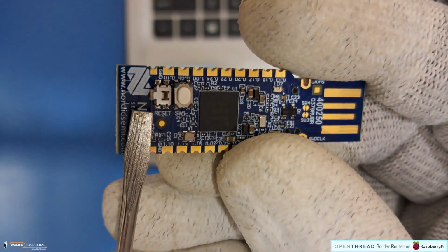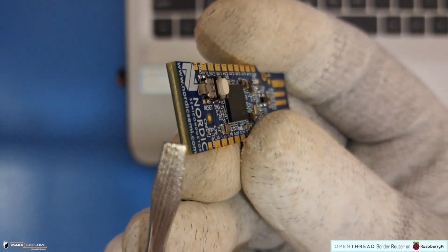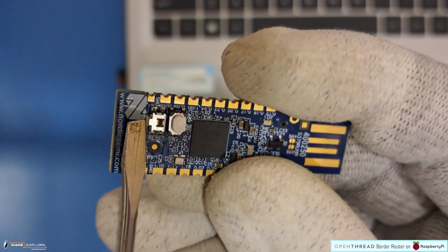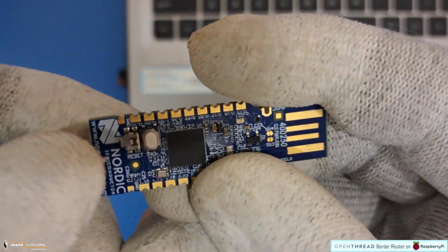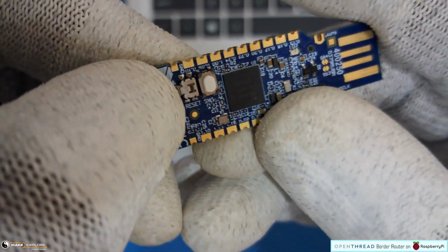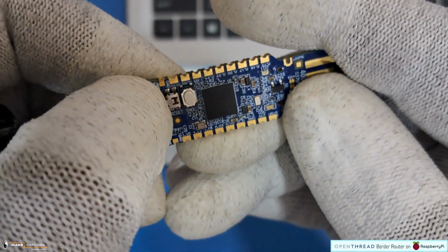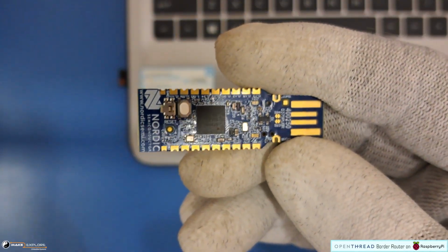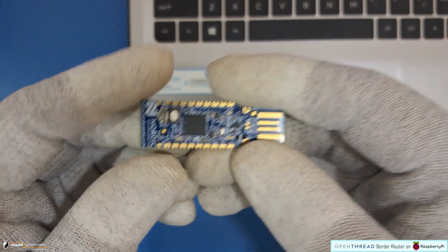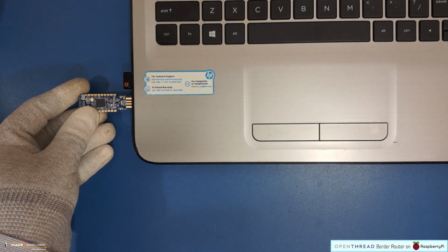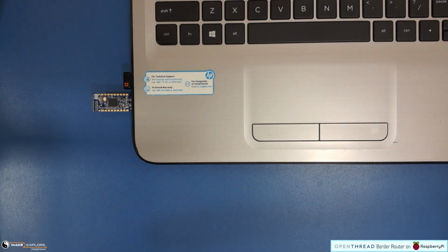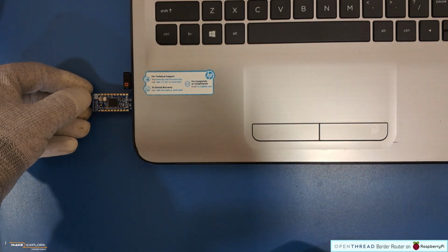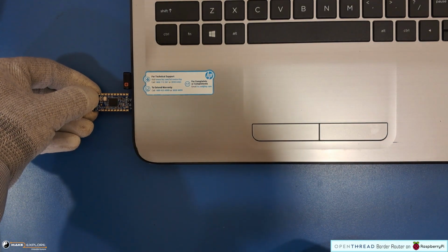About this reset button, note that the button does not face up. You will have to push it from the outside in towards the USB connector, like this. Please note, to enter into DFU mode, we have to press this reset button, not this big white user button. So, to enter into DFU mode, first plug in the NRF dongle to your computer's USB port. Like this. Okay. Then, we have to press the reset button once. Let me show you. Like this.